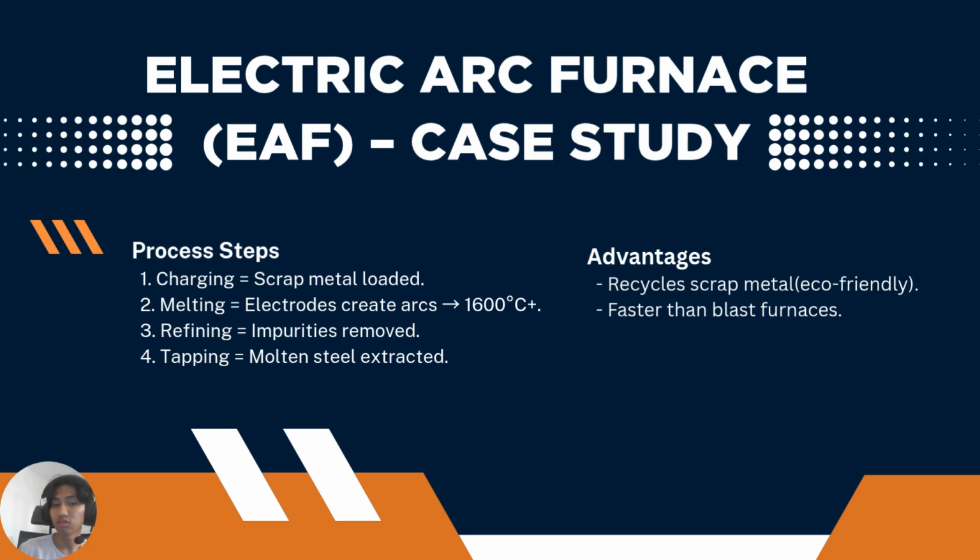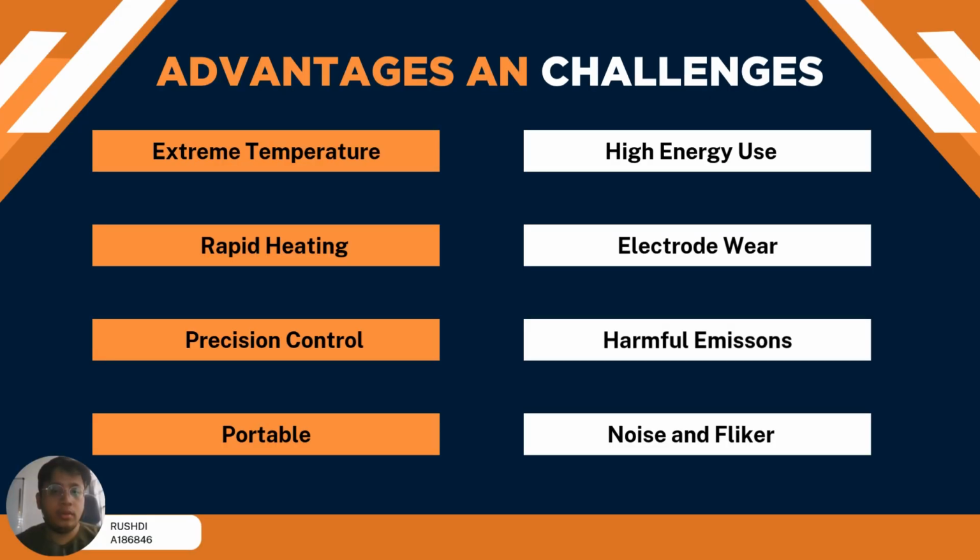The EAF has several advantages. First, it recycles scrap metal and consumes less energy per unit of steel. The second one is it's faster than traditional blast furnaces. That makes it both cost effective and environmentally sustainable. So, this case highlights how arc heating is not just a lab concept, but an industrial backbone for efficient metal processing.